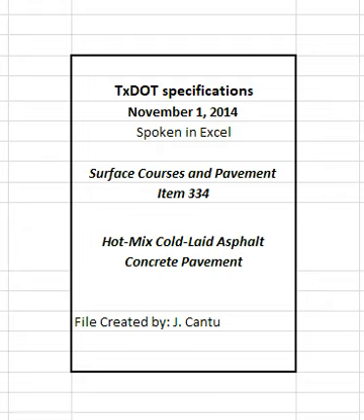Provide mineral filler, when used, that is sufficiently dry, free-flowing, and free from clumps and foreign matter as determined by the engineer. Does not exceed 3% linear shrinkage when tested in accordance with TEX 170, and meets the gradation requirements in Table 3. Table 3. Gradation requirements for mineral filler. Sieve size, percent passing by weight or volume. Sieve size number 8 with 100% passing. Sieve size number 200 with 55 to 100% passing.